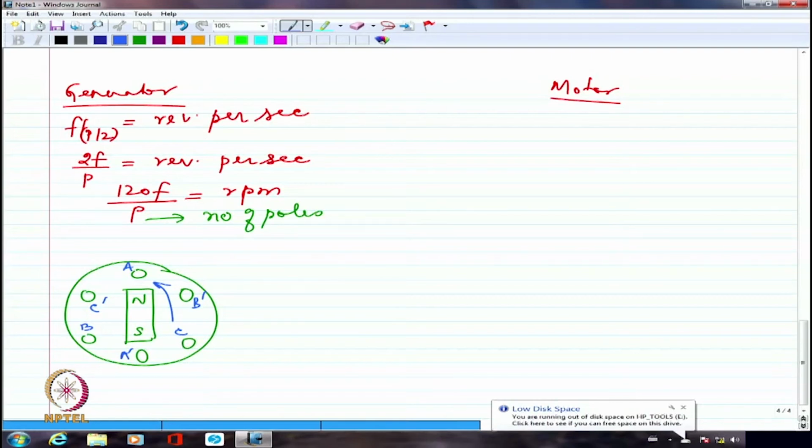It's not a problem. Most of the alternators, especially large capacity alternators, are connected in star and the neutral will be grounded, so that we are not going to get any shock, because you are going to have the body of the machine also being grounded. So if somebody touches it, there will not be any floating voltage. So you can definitely touch the machine. It's not a big deal. So this is the way generally it is going to work.